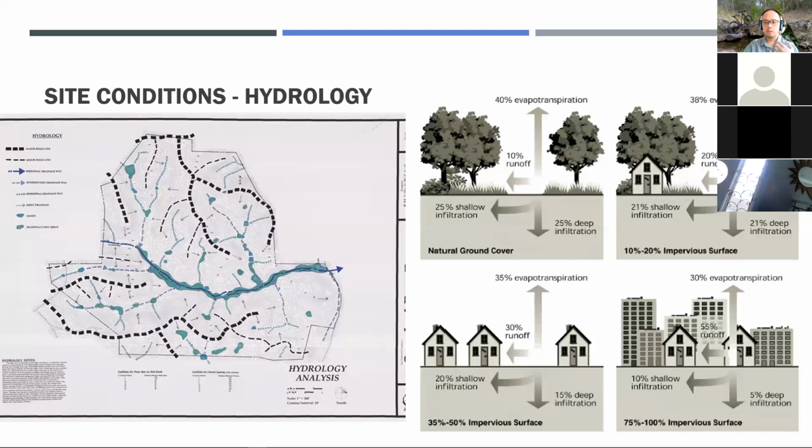Stormwater movements, infiltration, storage, and discharge are considered in the site inventory. The assessment of hydrologic conditions requires an analysis of the site surface and subsurface features, including topography, vegetation, surface water distribution, land use, microclimate, and soil forming processes and deposits.